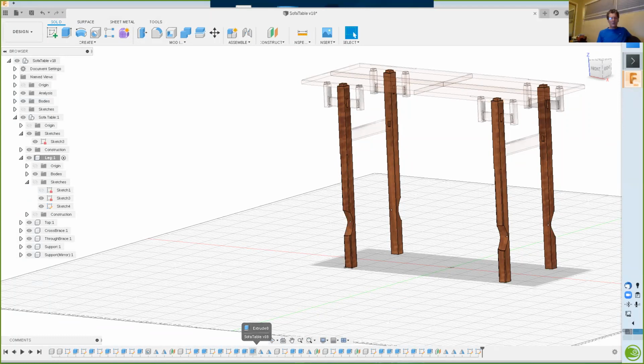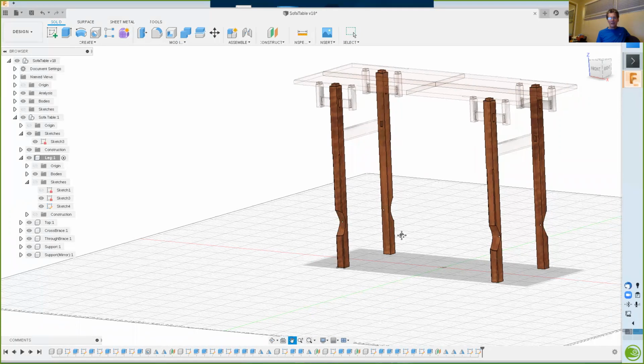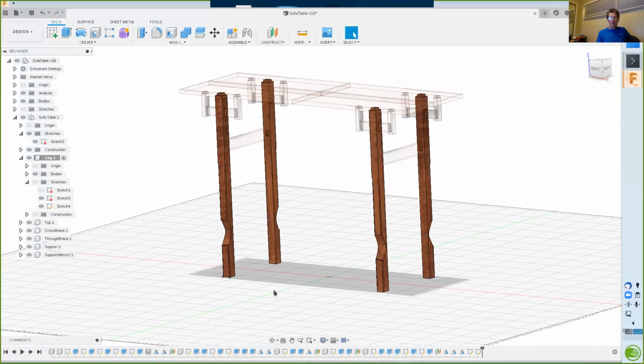Makes sense. So again, what we call that in parametric modeling is a parent-child relationship, and the child can't enter the world before its most recent parent, okay? Now, the interesting thing is it can have a lot of parents,